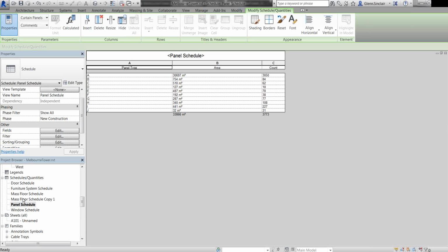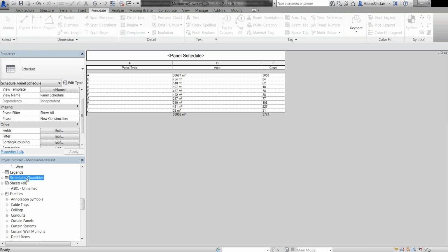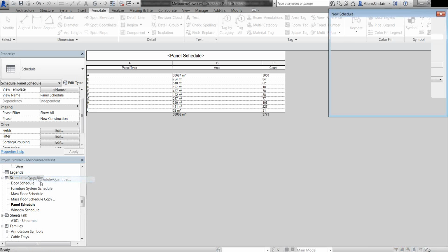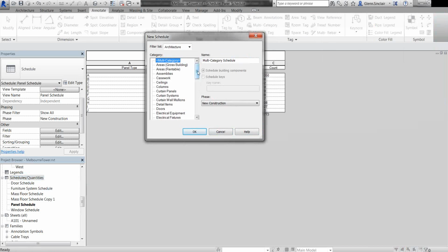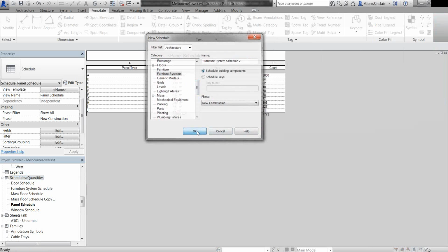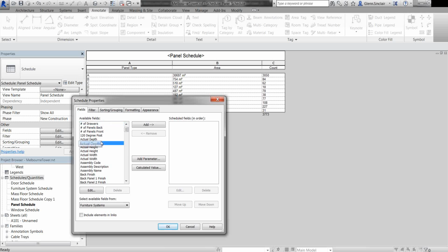The next little schedule that we're going to look at is just the items of furniture in that plan. So again, we don't want to be chasing ourselves around counting furniture items and things like that. We've got it in 3D. So rather than going around and counting, we'll just create a schedule of those items. So ours is going to be furniture systems. Very easy to create. Just have a few parameters in there. The description there. We'll put in the family and type of the object.